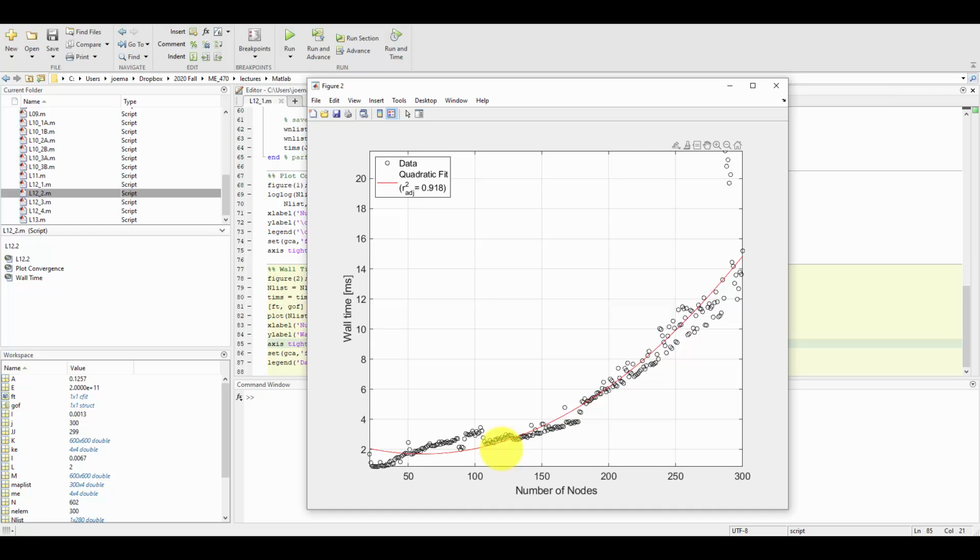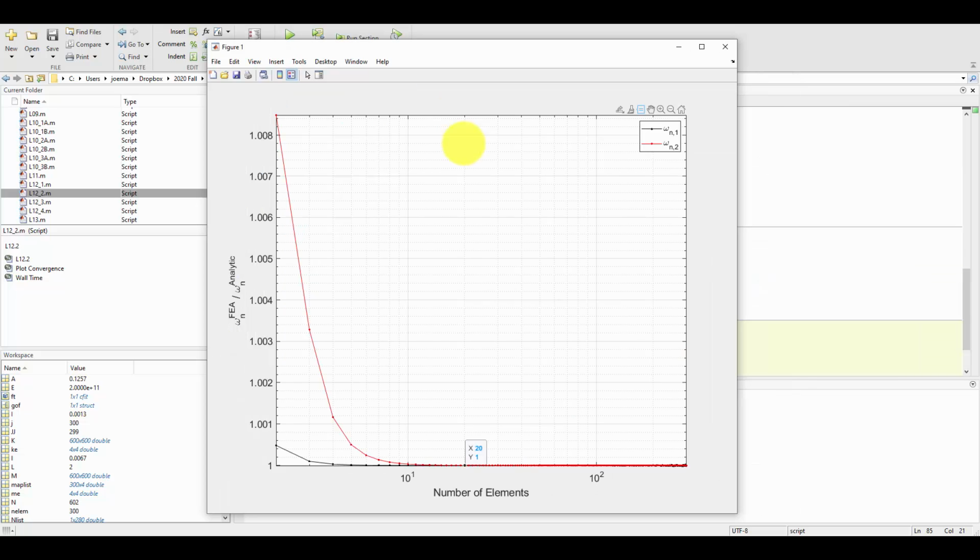So in the end here, we made our local mass and stiffness matrices. We slotted them into the global. We kept increasing the number of elements we used. And at least as far as the first two natural frequencies go, by the time we reached 200 elements, and before that as well, we converged to the correct solution based on the analytic approach we used in the previous section.